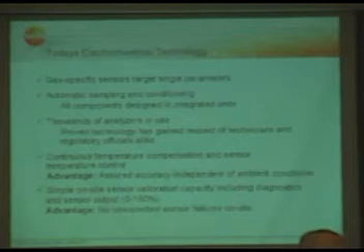A specific thing about infrared technology and also electrochemical sensors is that they are really dependent on the ambient temperature. That means if there is an increase or decrease in temperature, the sensors can start drifting. That's a natural thing of those sensors.